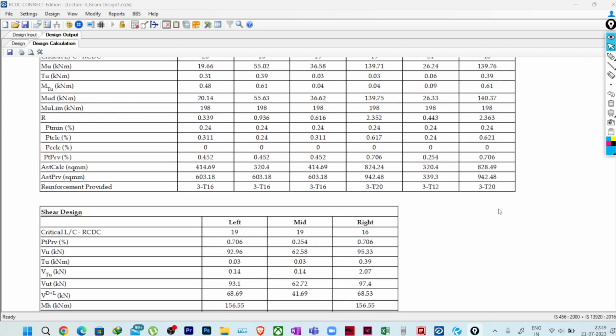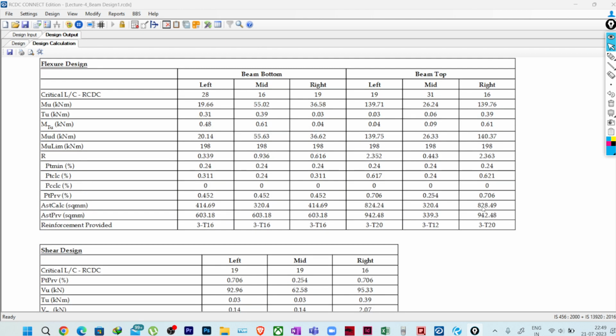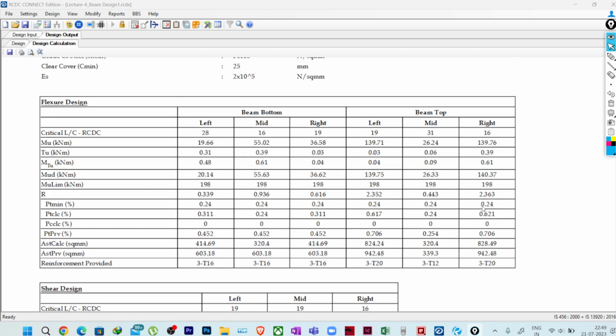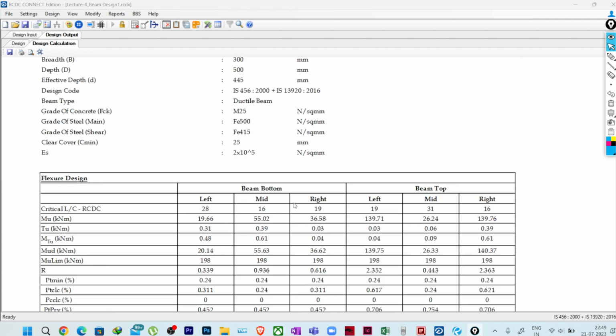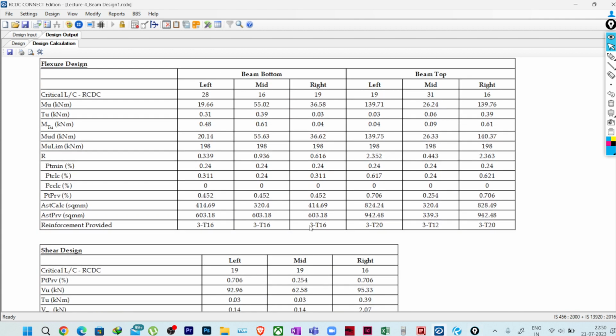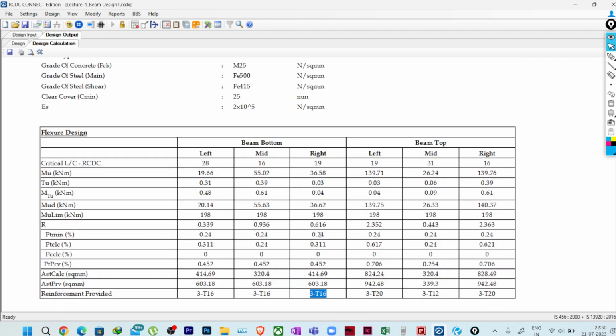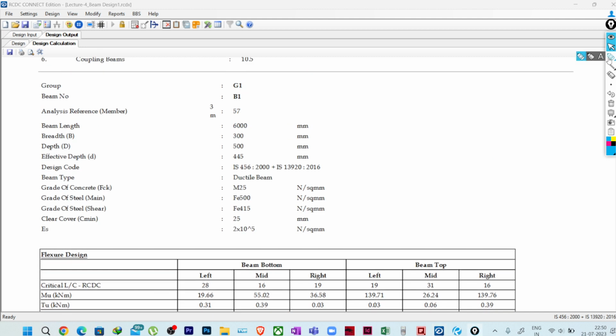in this design calculation, now it is coming 445, right? We have a 16 dia bar here, also a 20 dia bar here. So maybe in this case it will be reduced. Let me check. If I use this 16 dia bar, the provided minimum reinforcement dia is 16.